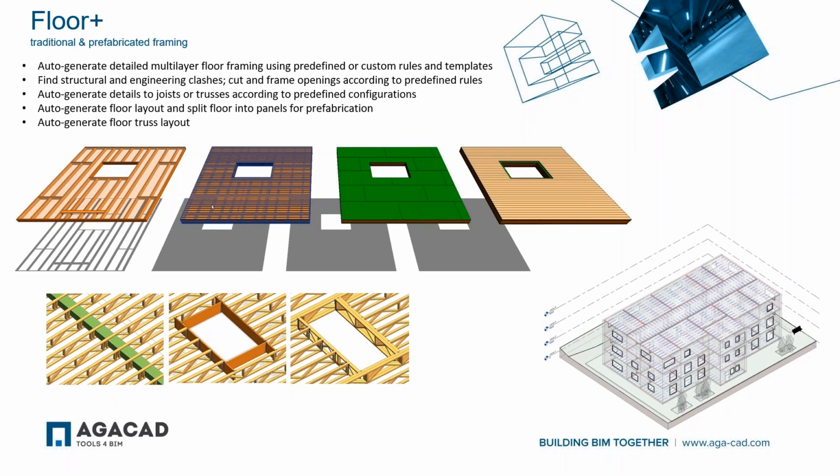The package also includes Floor Plus, which also deals with traditional prefabricated framing. Same thing here. We can auto-distribute structural framing members within our floors. We can create openings and frame around those openings. We can also create floor trusses and create openings within those trusses to accommodate any sort of MEP services passing through.